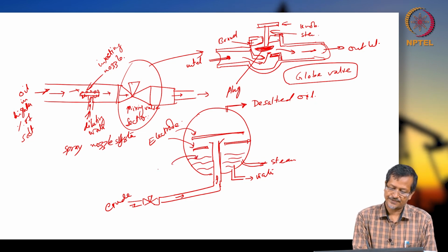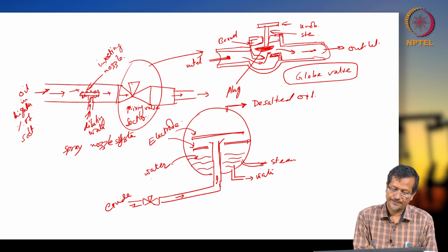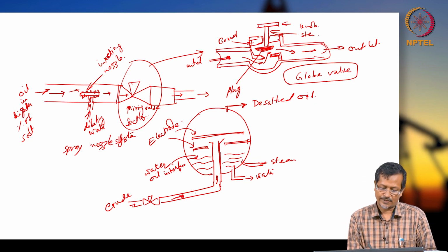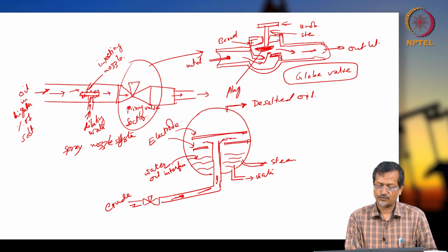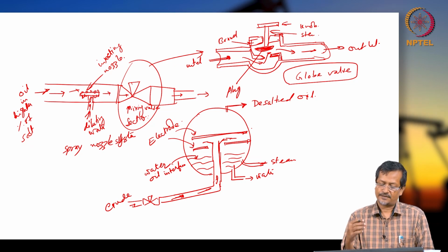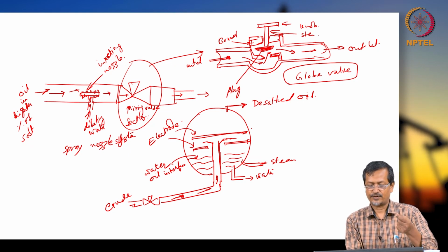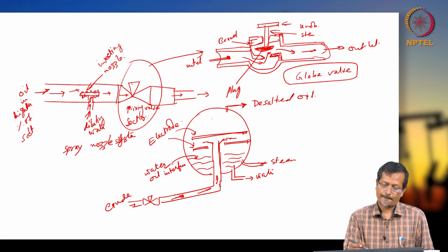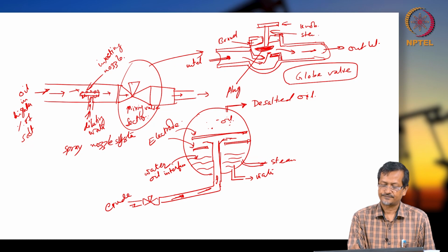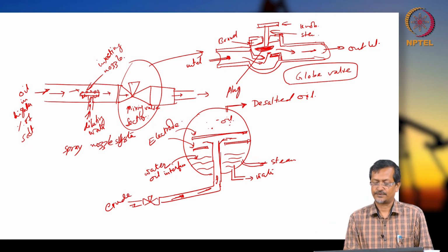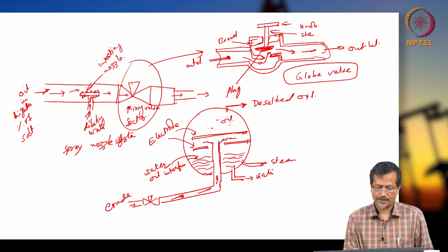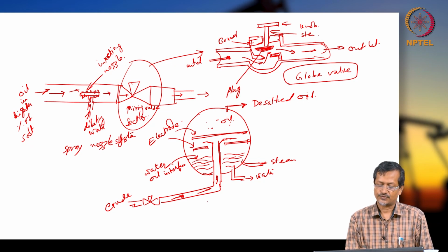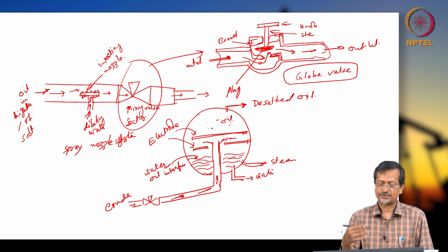So this is the water-oil interface. You can see this crude oil moving through this pipe, and it will be spreading here. When spreading here, there will be two electrodes, positive and negative. Using the positive and negative electrodes, you are separating small particles, and the oil will create a layer over here. The oil you can take out from the top section, and water is heavier, so that will create a layer at the bottom. From the bottom you take water out. So this is a simplified diagram of an electrostatic treater. These electrodes are separating.